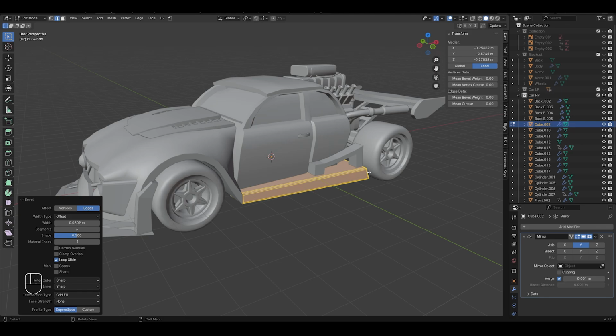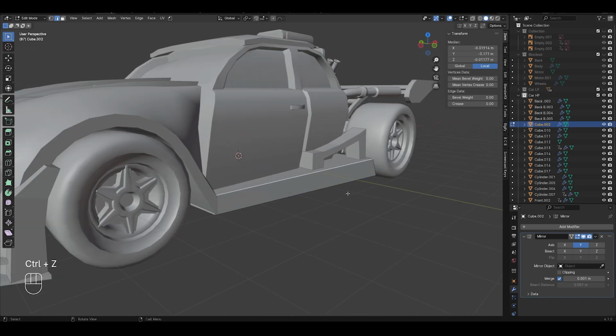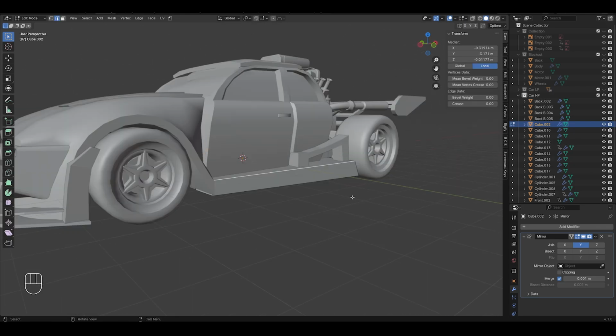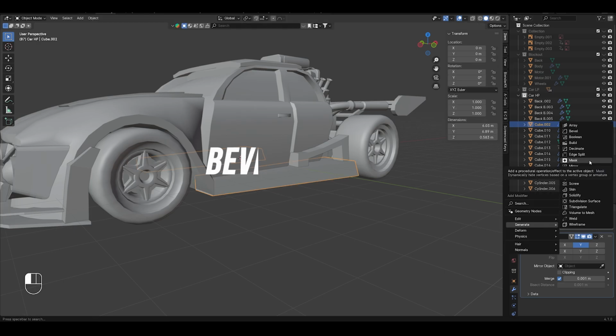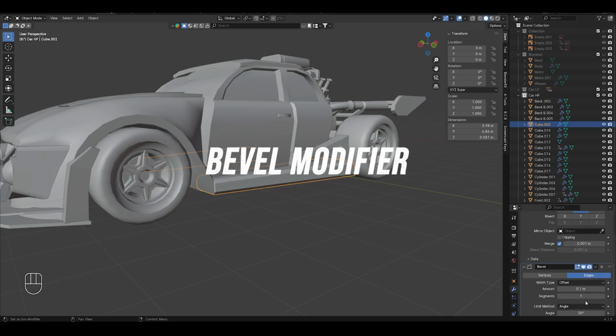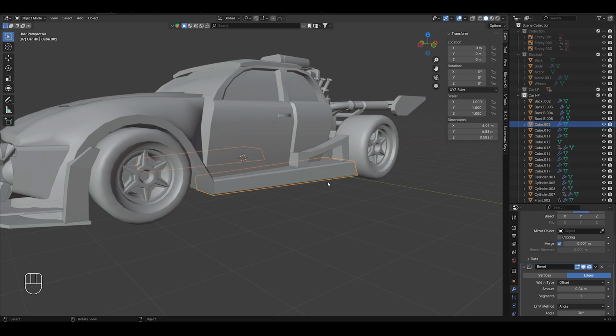But in Blender we have 2, even 3 different bevels that you can apply to the geometry. One of them is the bevel tool that changes the forms, which can be applied to only one edge if we need it more smoothly. Meanwhile, the bevel modifier will apply to your whole object, and you will use the same settings for all edges. To demonstrate it, I'm just gonna add a bevel. We will see that everything applies equally to all the edges that you have.